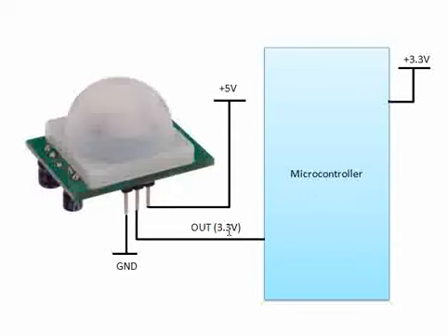If you have interrupt enabled, automatically it goes to the ISR and executes. If it's a GPIO, and if you don't have any other complex application, you can just poll the GPIO, and every time you see that it goes high, you can perform the respective action from this microcontroller.